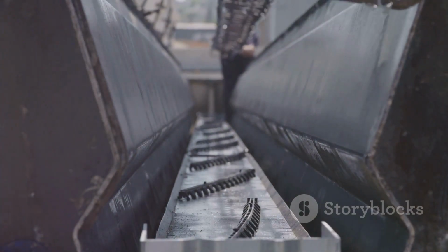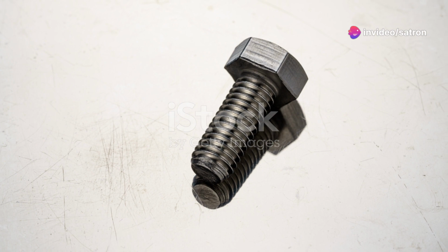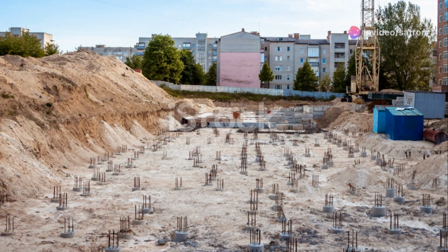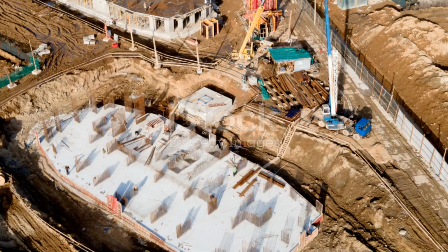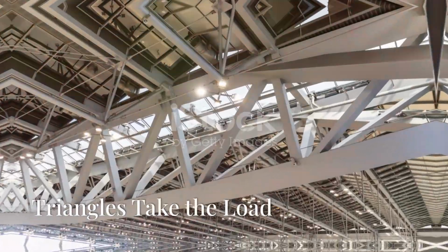And then there are base plates. These are thick plates that are placed at the bottom of columns to distribute the load over a larger area of the foundation. They prevent the column from punching through the foundation and ensure that the weight of the structure is transferred safely to the ground.